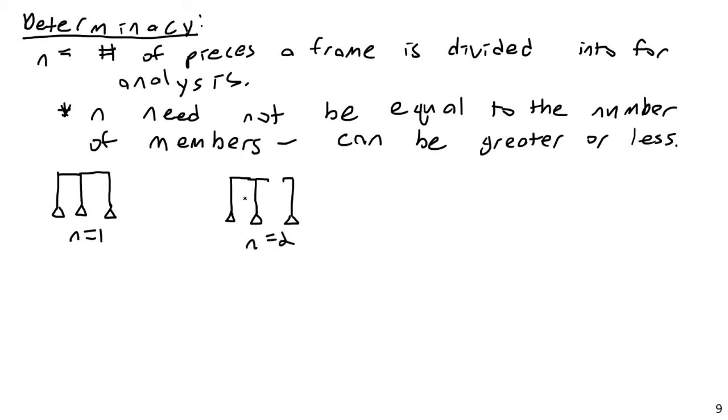What if I made a cut plane across here? I basically cut out the top beam. So I would have this here, here, here, and then the bottom portion of the columns. Well, what would n equal? Yes, very good. n equals 4 in this case. And then I could keep going. Let's say I separate it out like this, this, this, this, this. I've got my supports here. What would n equal? Yes, very simple, n would equal 5.